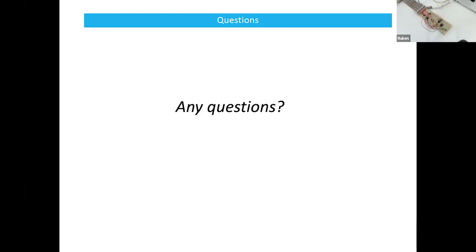You can. So the driver, as soon as the LED script wants to access the driver, that's no problem. It'll send a read or write system command. Let's say it wants to turn the LEDs on, it'll send the write command. So we're writing to the GPIO registers. As soon as my driver sees a write to those GPIO registers, I activate what's called a spin lock. And that locks out any other process from accessing those GPIO registers. And the reason why it's called a spin lock is any other process that tries to access those registers is sent into what's called a spin.